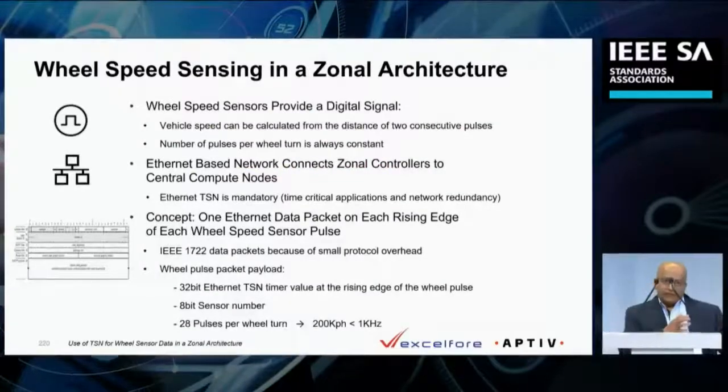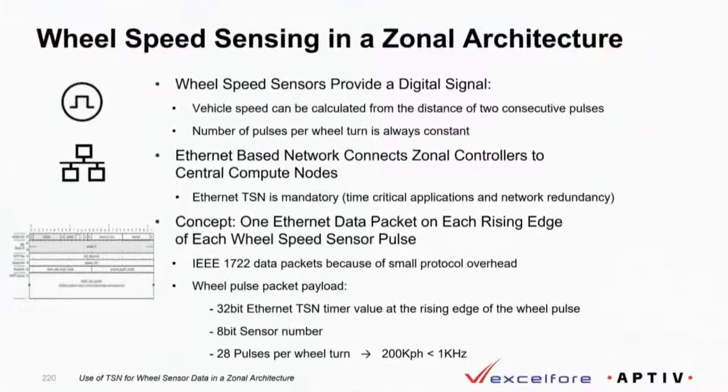So you take the wheel sense, which is analog in the previous slide, and ask how you convert it into a more digital form for our calculations. Wheel speed sensors provide a digital signal, giving you these timer ticks. Essentially, the faster the wheel rotates, the faster the ticks come. But the distance is constant, so you know how the wheel is moving.